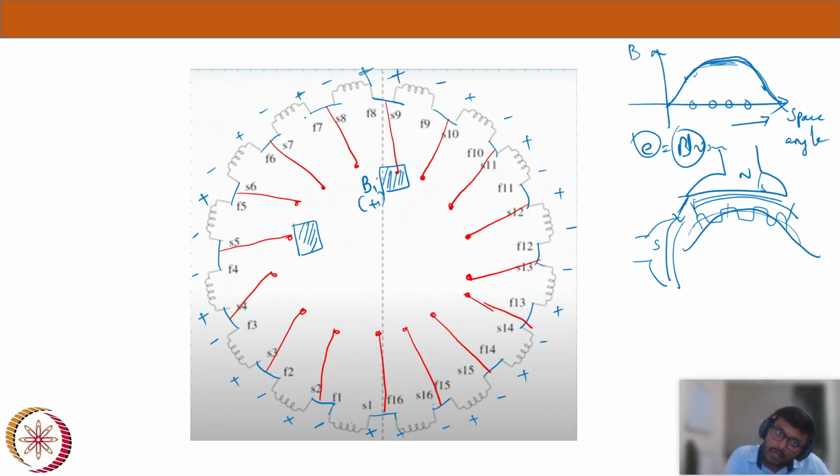In the same way, let's go through all the terminals and see where you are getting the same kind of positive or negative. Now if you see, I have placed the brush here. Why? Because you can see here that consecutively you are having a negative, right? So I will do that as a second brush, B2. It is nothing but a negative brush.